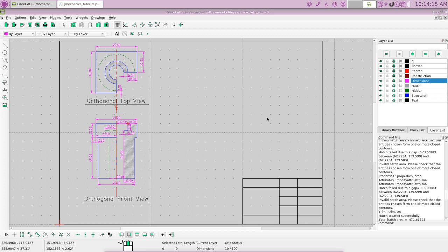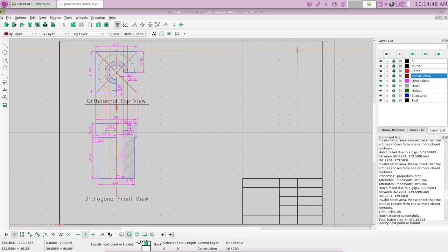So if we just click onto the construction layer here, you see all these lines we have. We'll go on the construction layer, and we will draw a line. Okay, free snap, and draw a 2-point line right from, say, here, and let's restrain the vertical, and let's go up to, say, here. Okay, now from this end point of this line here, let's go snap on end.